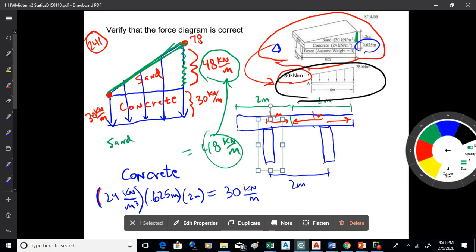I've done this with soil loads on a dam once too. I've done this in different situations. You work your way through. If you've got a roof like this building here, you look at the weight of that slab up above and how much of it you would assign to each beam, and that's how you come up with the load on the beam. You might also have a snow load and things like that you add into the weight of the concrete. You might look at some of these other things, snow and wind.